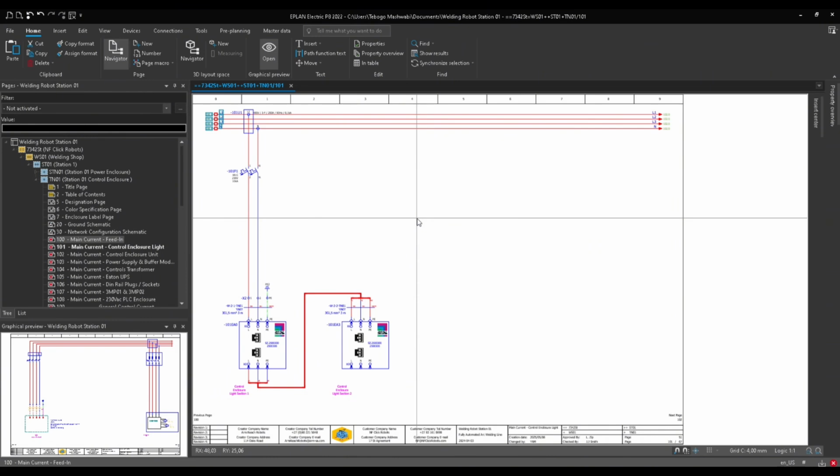Electrically inside the cabinet, the panel builder will wire them together because they are physically connected. But inside EPLAN schematics, we break them and continue them elsewhere. Interruption points are normally called interruption markers or interruption nodes by some people, and they are special symbols which we use to break a connection. They are essentially virtual connections which maintain electrical continuity while improving schematic clarity. So we use them to avoid clutter inside our schematic pages.